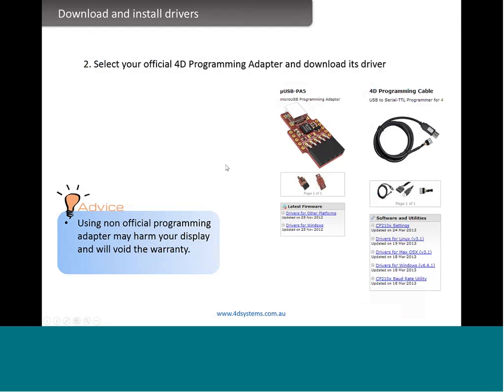And actually, I work in support, and I know that some people actually destroy their bootloader by using third-party programming adapters. The cables are not expensive, and you don't want to destroy your display just because of a few euros. Please use the original programming adapter for your development process.